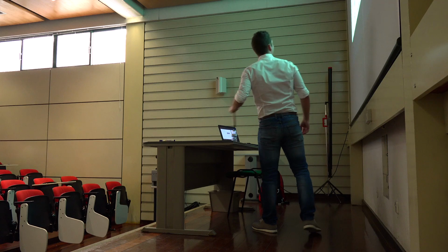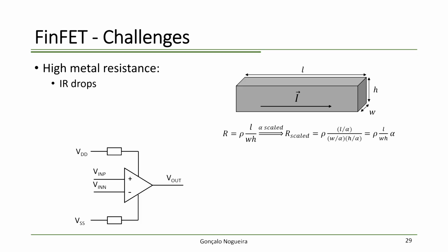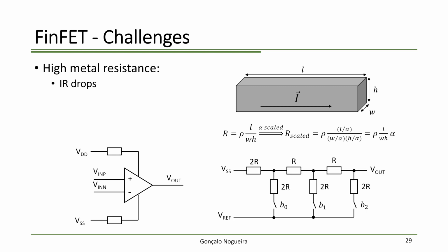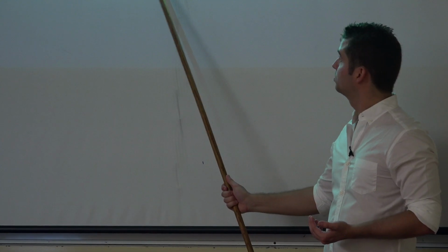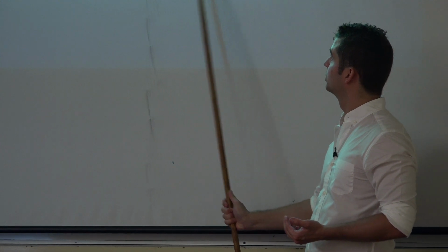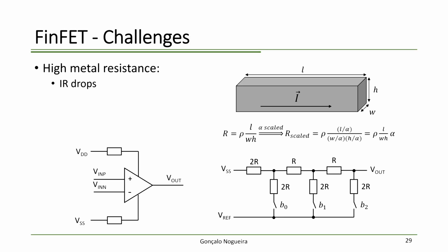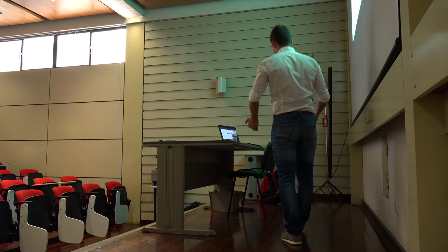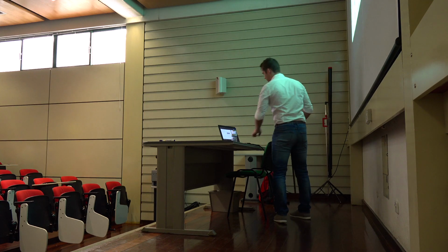Imagine that you have here 200 ohms parasitic resistance, 200 ohms here, and that this uses 1 milliamp current. You're losing here 0.2 volts. You're losing here 0.2 volts as well. This degrades the performance of circuits. This is also seen, for instance, in R2R DACs. You've got a parasitic resistance between this point and this point, this point and this point, also after the switches, between the switches and the resistors, and this can become a problem if you don't tackle it.